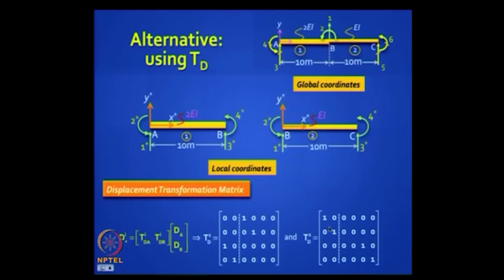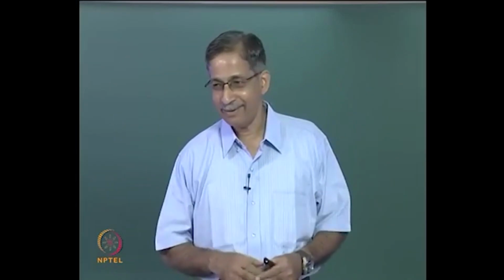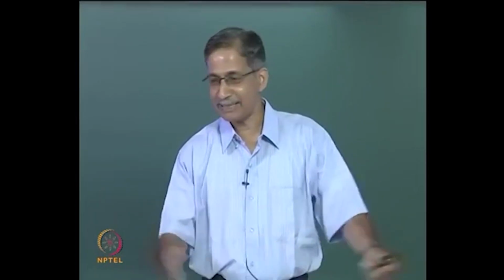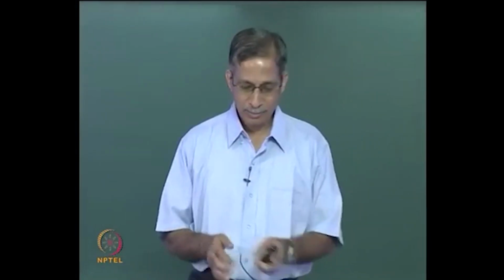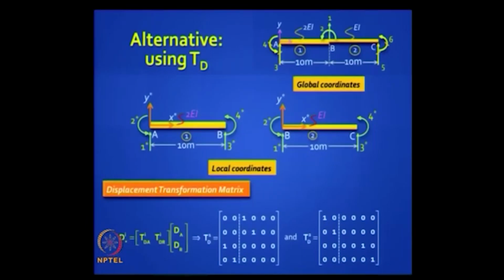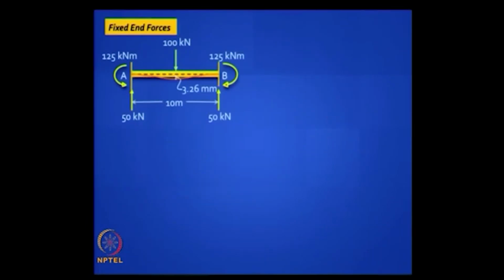Likewise, okay. And I have done a partition here because I am separating out the active degrees from the restraint degrees. Is this clear? Have you all got this? Easy to do. Two approaches. The advantage with this approach is you do not have to worry about the slotting. The matrix multiplication takes care of everything. Let us see both approaches, clear? And you should know both. Can I move ahead? Okay. Next you have to find fixed end forces, which you know the formulas.